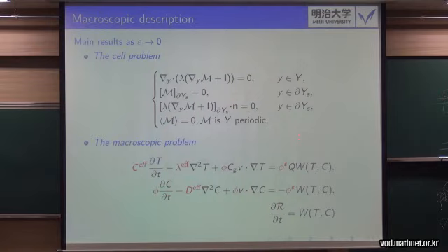So we have this form where phi here represents the porosity of the system, and this is the surface porosity, and this is the effective thermal diffusion tensors here. So at this point we see that what we are able to achieve with this homogenization step is to be able to guess the form of a microscopic model that we can use for the study of the phenomenon of interest. And also we have effective parameters coming into the equation.